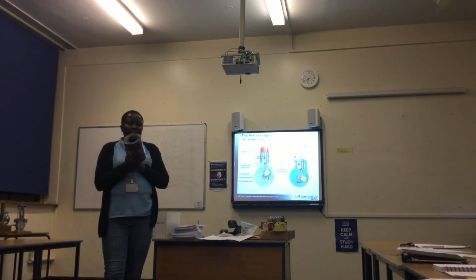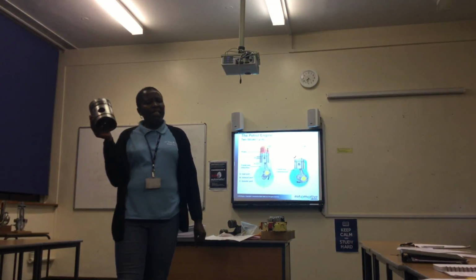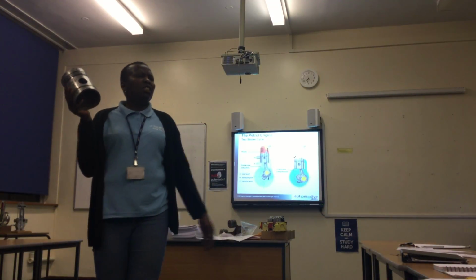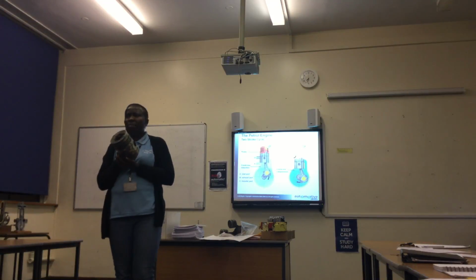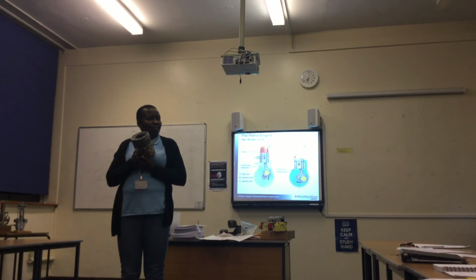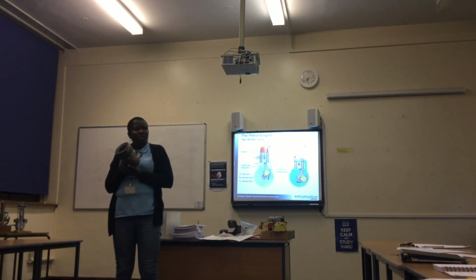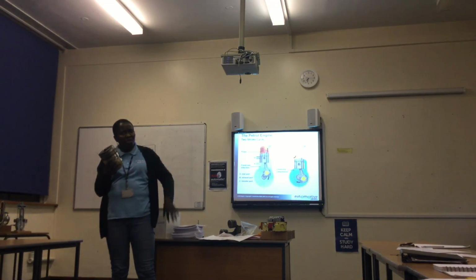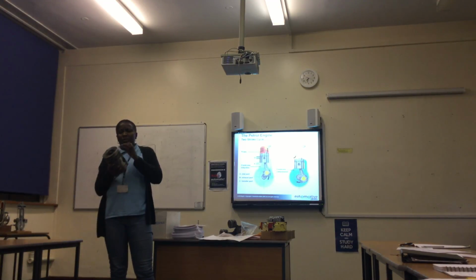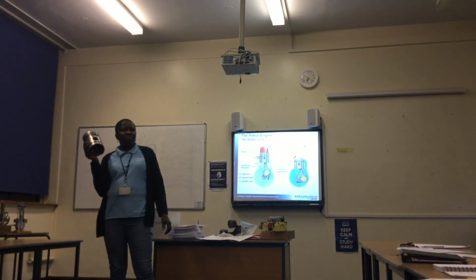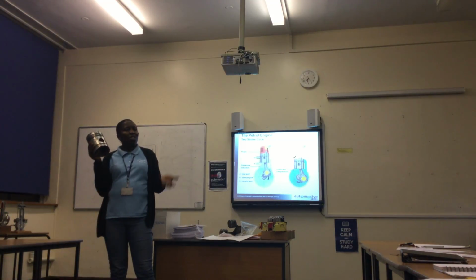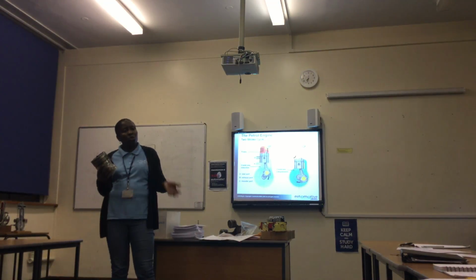At the end of the day, if the oil scraper rings are defective, broken, or worn out, what do you think will happen? The oil gets in the mixture, isn't it? Oil will get in the mixture. Yes, we can have excessive oil consumption, black smoke out through the exhaust, too much oil going into the crankcase. And what will happen if the compression rings are worn out? Loss of compression. During the compression stroke, no compression, loss of power, the engine is not going to pull.